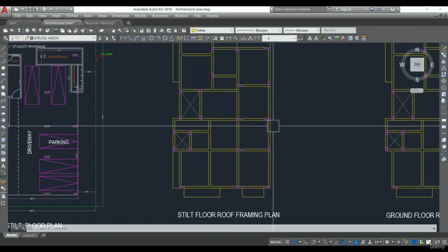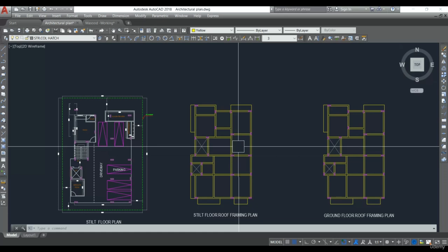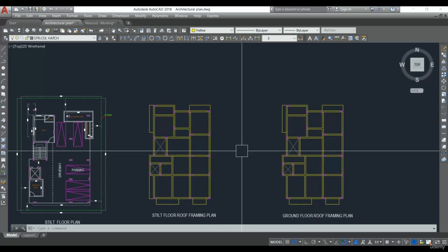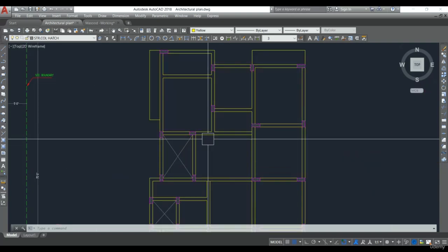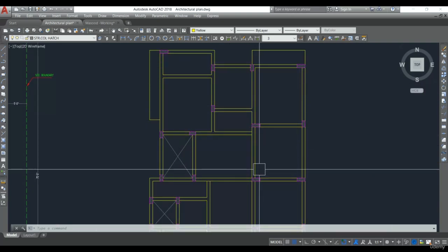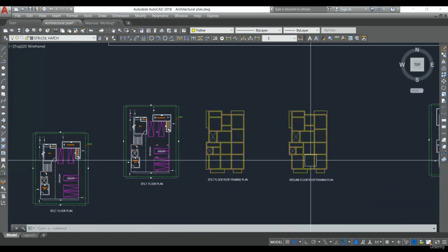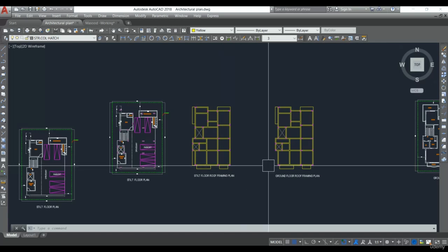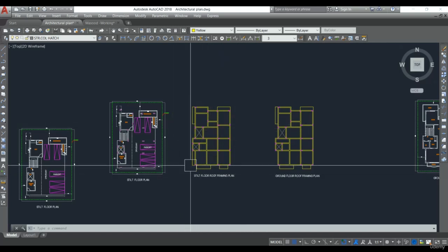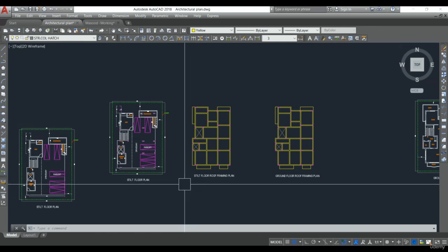And here I have explained you the concept of primary beam and secondary beam also. And mainly the outer beams have to carry the load of the main wall, and inside there will be partition walls. So for that also we have provided beams to carry the partition wall load. So this is how you have to make the framing plan. Now it is done. Next let's make the column grid layout. How to make the grids, that I'll explain you, and let's name the beams and slabs.